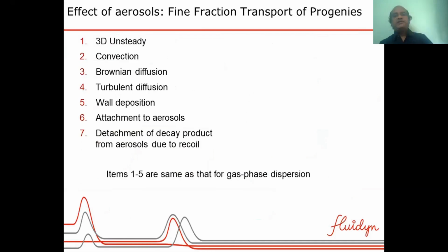These problems involve 3D unsteady simulations, convection, Brownian diffusion of small particles, turbulent diffusion, and deposition on various walls, horizontal walls or the ground, floors, or other surfaces like table surfaces or the human body, or they can be inhaled by human beings or taken up by plants. We also have to model the attachment of the decay products onto the aerosol, and once they are on the aerosols, they again decay.